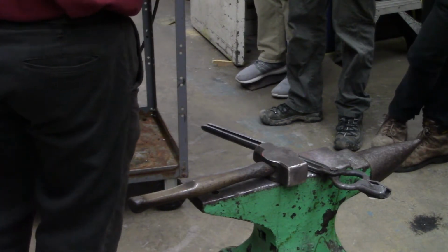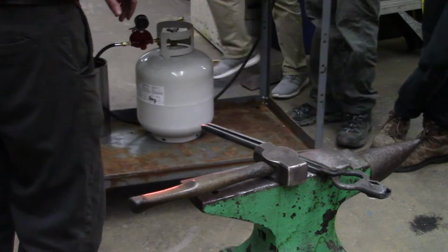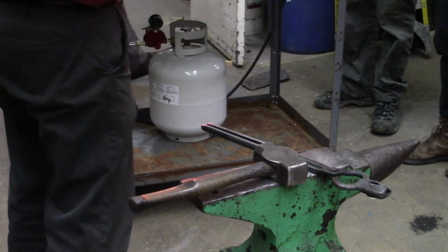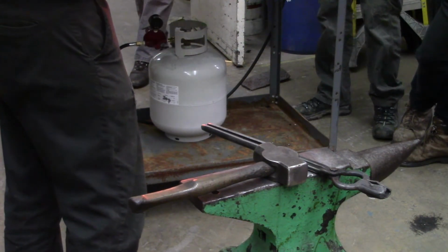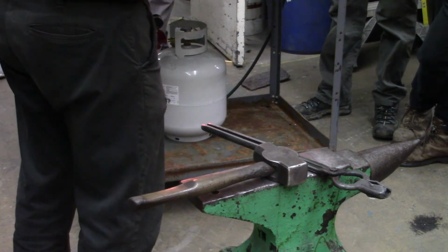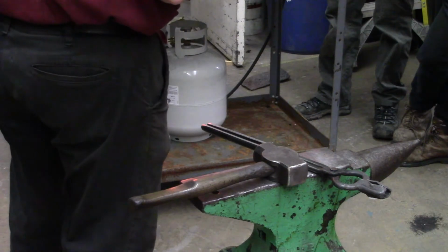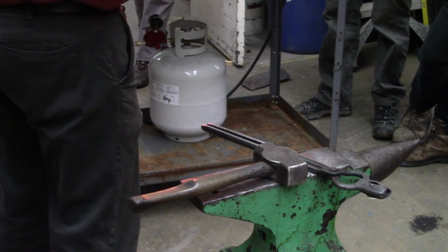Is that because of the nickel? Well, the nickel and the chrome. There's actually not so much nickel in the billet, because nickel all by itself is actually fairly soft. The steel has 3% chrome, 2% molybdenum, a little bit of vanadium in there, and then whatever carbon content it has that I couldn't verify today.